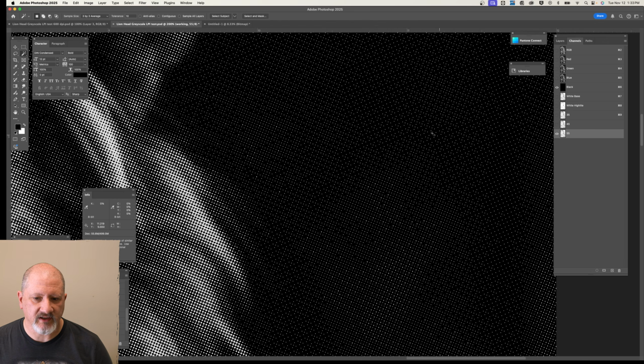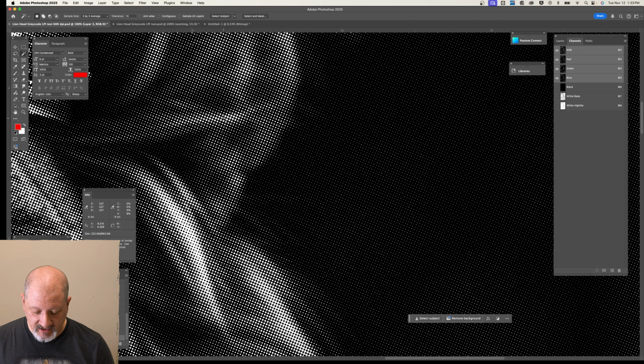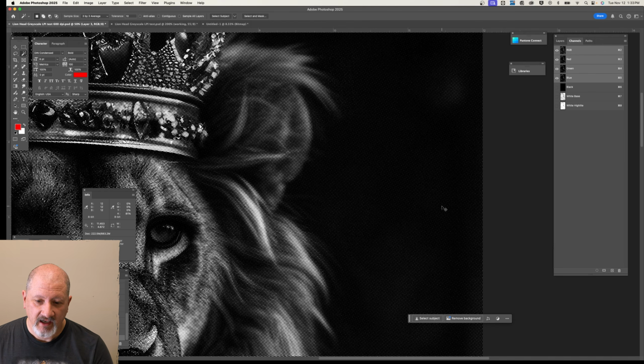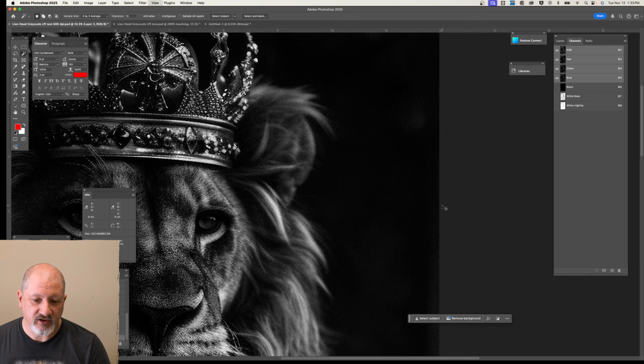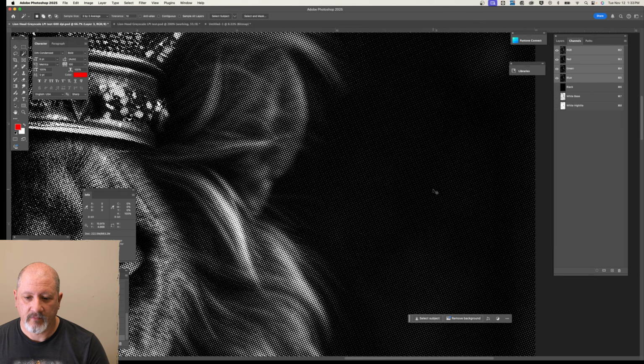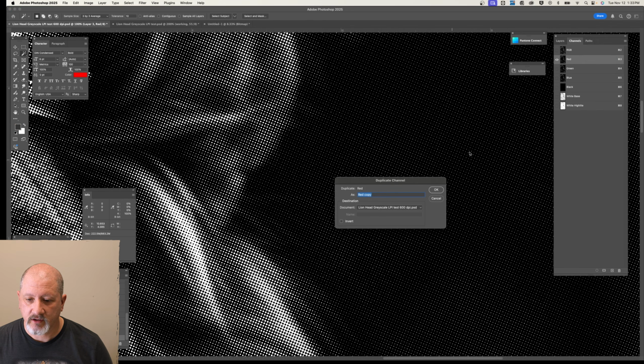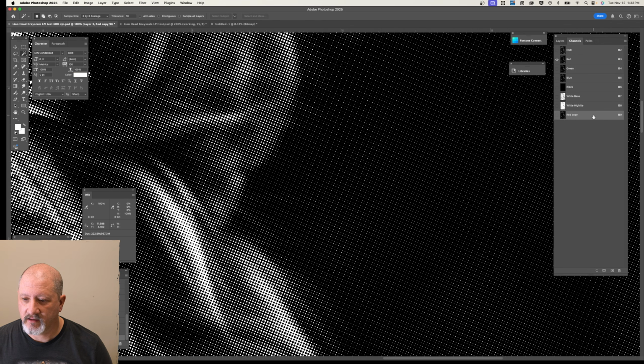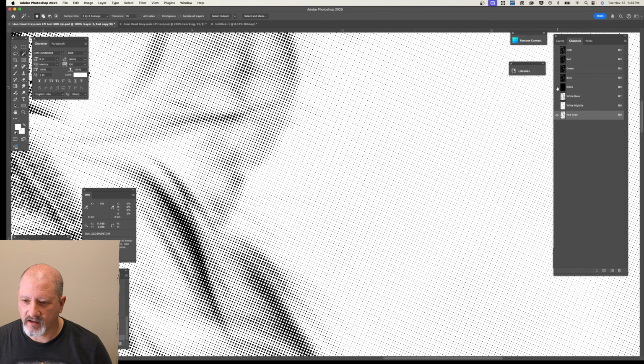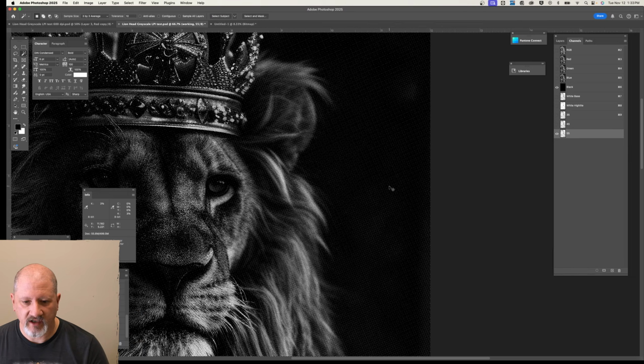What we can do for resolution, you can see these look like a dice that rolled a bunch of fives, versus 600 DPI gives us much better resolution. Now, as I zoom in and out, we have that interference pattern. So I'm going to duplicate that, click OK, double click, spot color, OK, invert. Just need to select it, invert it, look at it on a black background, infinitely better.